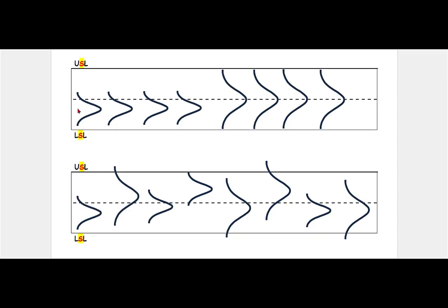Let's take a look at this one. The average is pretty consistent over time. It's not where we want it to be, but the variability still looks good, and we're not making defective products yet. And then at this particular point in time, the average shifts up, but the variability increases, and it's consistently bigger than these. So it appears that we are not making defective product at all during this time sequence. However, the variability has increased even though the average has improved.